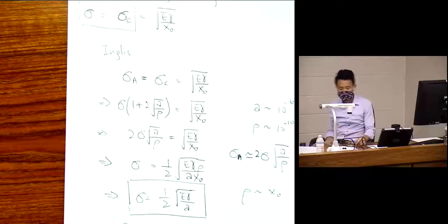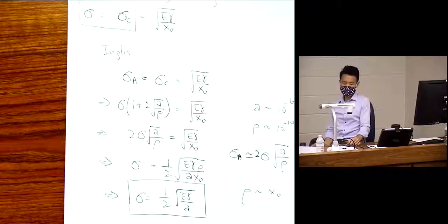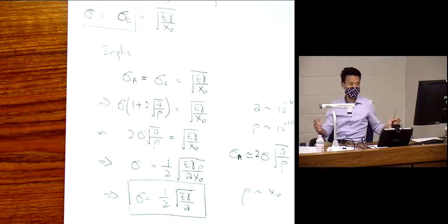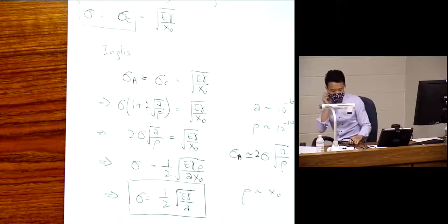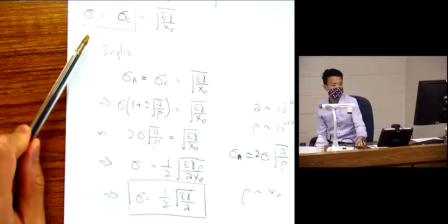So now let's examine, does this make sense, right? As the length increases, as the flaw size increases, what happens to the strength? It's smaller, right? A larger crack means that you're going to measure a smaller strength. So this actually, in the end, gives a much closer expression than the earlier one.